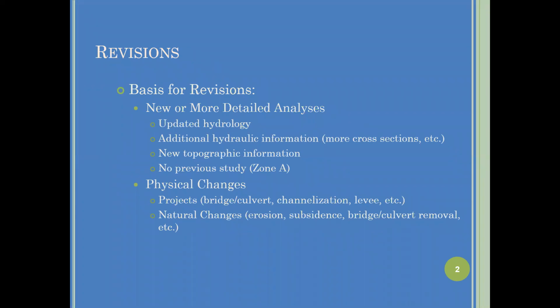In 2016, Mile High Flood District adopted the NOAA 14 Atlas, so that would be an example of updated hydrology. Also, hydraulic information may change. There may be bridges or culverts that were installed, there may have been channelization, or levees may have been built.